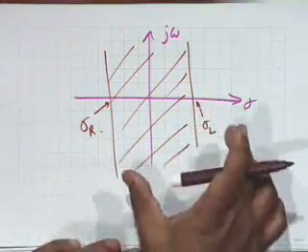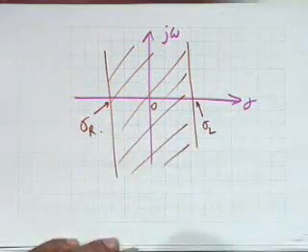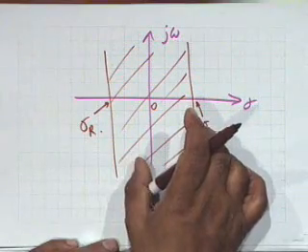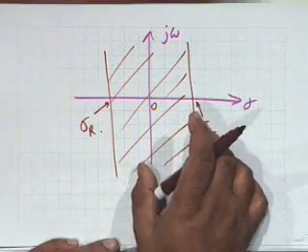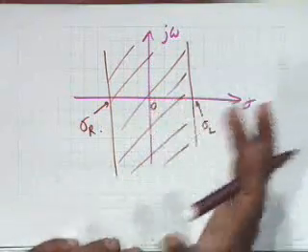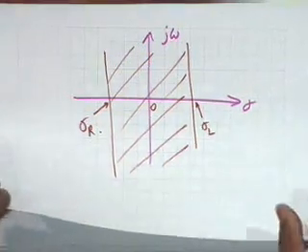All right. It may be bounded between two sigmas. Sigma R is negative, this is 0, and this is sigma L. Obviously, for such a situation, the Fourier transform exists because it includes the j omega axis. ROC is not necessarily infinite, it can be finite also. To show this, we have to consider three possible cases.